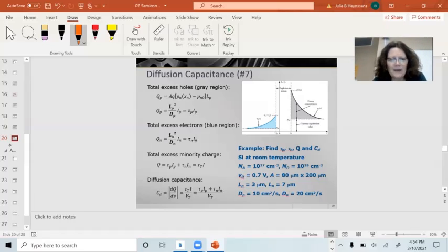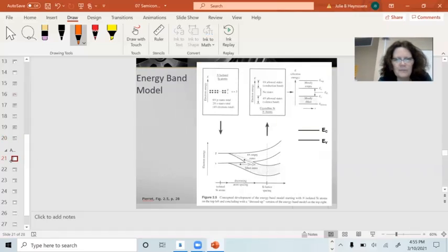The diffusion capacitance depends upon this tau here, which is like a time constant. It's how long in time, as these carriers are moving, it takes for them to decay away. If we look at this equation, we could cancel IP out, and tau p is basically those two constants squared: LP squared over DP squared. It's just an equation, and that's not really all that important at this level, but just so you have an idea that these are derived and they do come from somewhere. Okay, this is good. This is what I need to spend more time on.